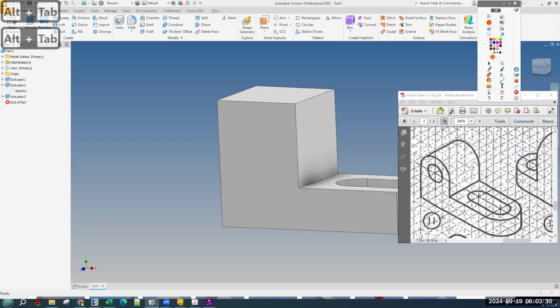And to round over the edges, I'm going to use the fillet tool, where we are going to choose this edge, and it will round it over. And even though this is one continuous arc, if we make the size of the fillet on this size the correct size, and this one the correct size, they will make a smooth face like it's supposed to. And the question is, what is the dimension of the radius or the dimension of the fillet?